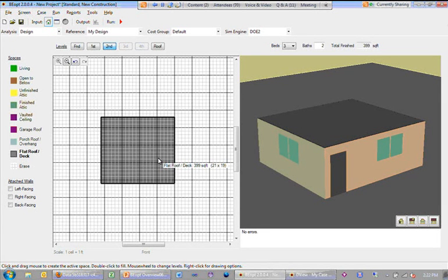And when you do that, you want to not just take the average thickness and an R value associated with that, but because the U value being the inverse of the R value as a function of thickness, what you really want is the correct effective U value. And so average thickness won't necessarily give you the right answer in terms of an effective U value for the entire area.